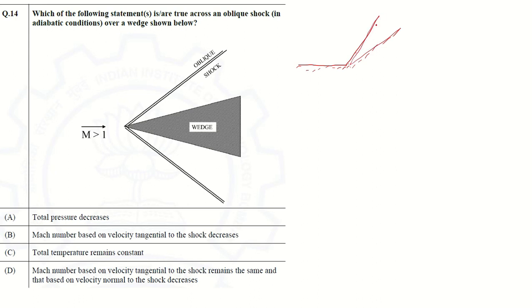Now the flow is going like this, and due to this it is converted like this. Mach number is greater than 1. Here is the Mach number M2. If M1 is greater than 1, M2 is less than M1. Why? Due to the oblique shock wave. A normal shock wave is the same, a little different, but the oblique shock depends on beta, the oblique angle. Here pressure is going up, temperature is going up, density is going up.